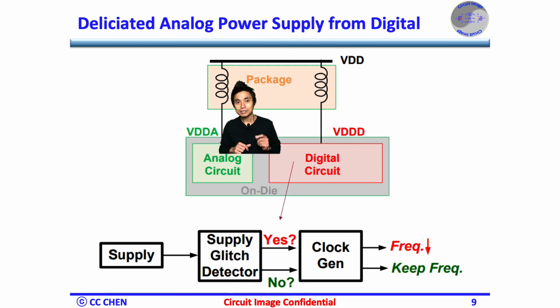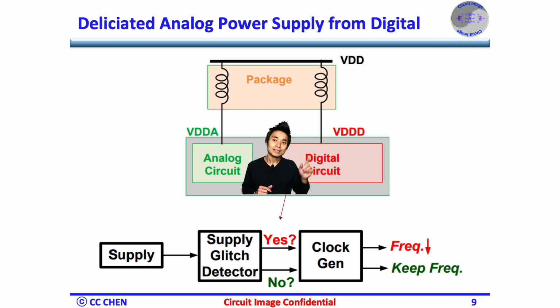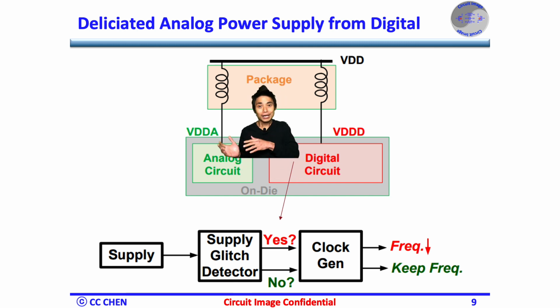Correct. The analog supply is usually quiet for most amplifiers, but the digital supply is quite noisy and will further couple to the analog circuitry and corrupt the normal operation. To avoid that, we must isolate both analog and digital supply to avoid the noise coupling. Again, for some circuitry tied to the analog supply like the TX output driver, we must also put as much decoupling capacitor near the supply pins of the switching transistor as close as possible.